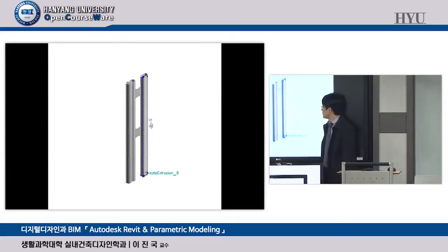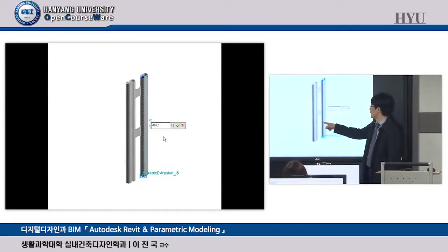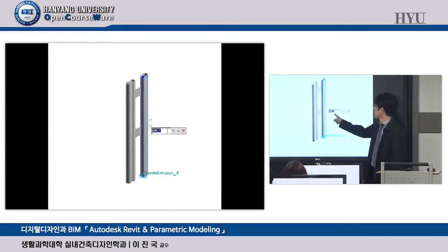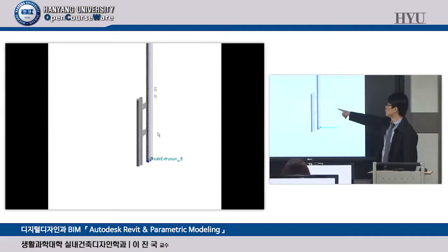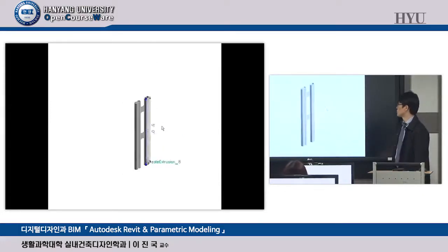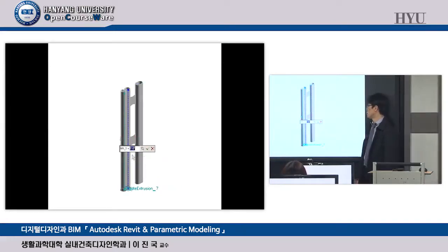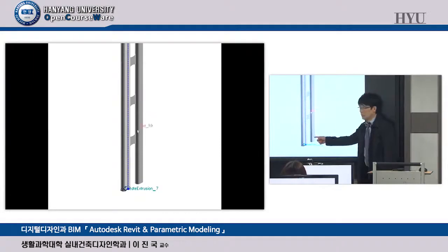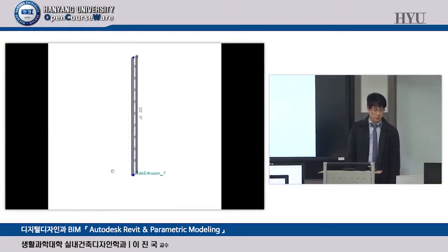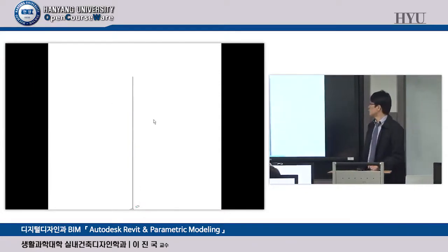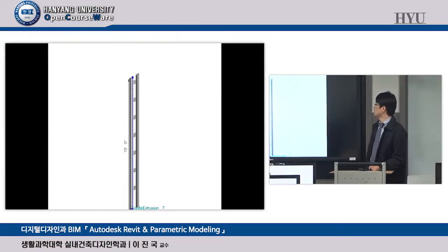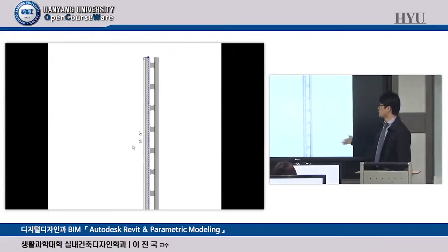Take a look. Front height is user input, and rear height is exactly equal to the front one. But if you type your user input, that one is going to change that way, okay? So undo that and go back, same as the front one. At this time, change the front one to 20, and then the rear mullion also changes exactly the same as the front one, okay? Change 20 to 15 and the rear one changes equally, and change the view, right view.